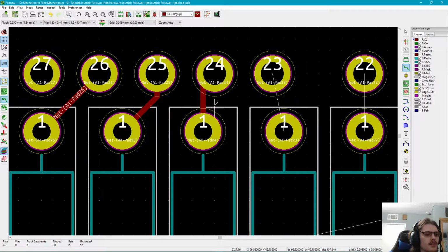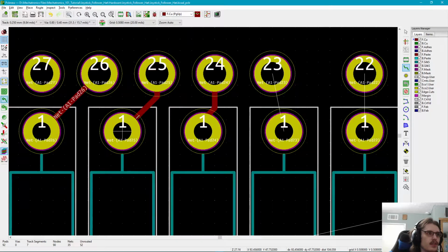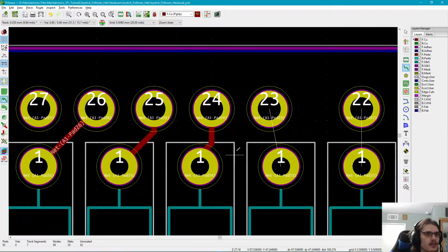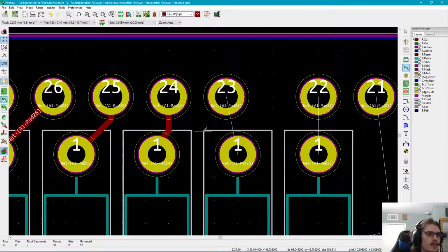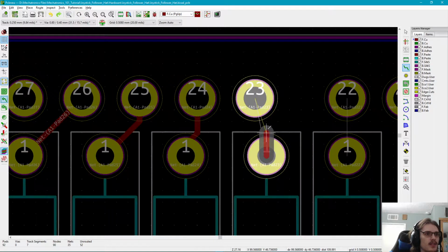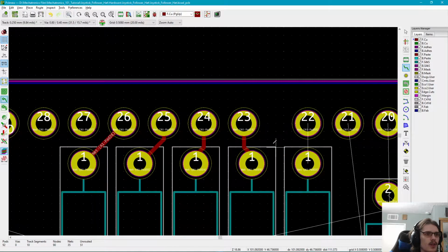This one should, actually, let's change this a little bit. So one thing you want to keep in mind when you're making traces is try to avoid right angles, or sorry, acute angles at all points, at all costs. The reason for that, like right here, it's an acute angle. This is technically an acute angle too, I guess, but it's not as bad. What we mean by acute angles that are a little more worrisome is ones that are really close, or maybe 30 degrees or less.